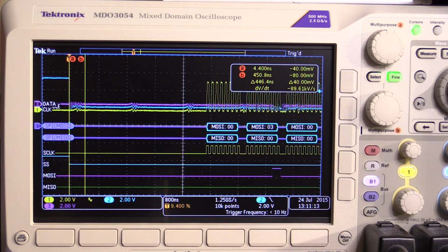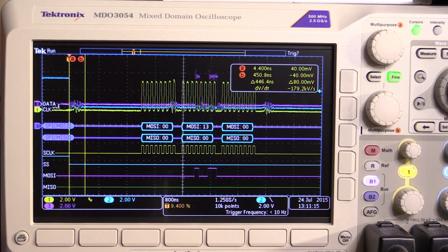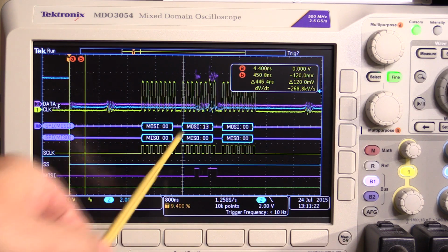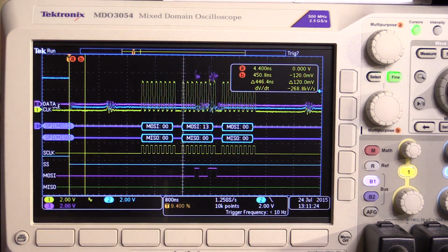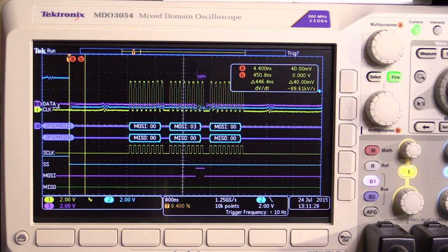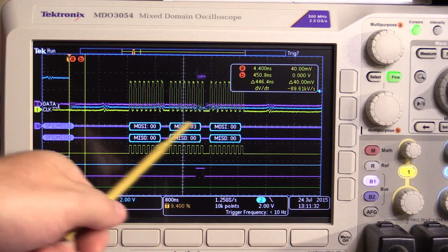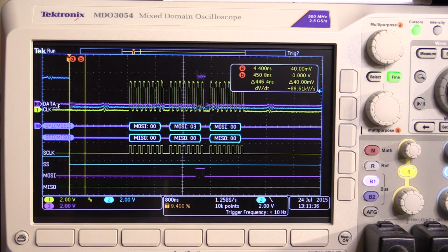So there's a bit being set and reset depending on the mode as I go in and out of unipolar, bipolar. And if I power up and down, you'll see that I've got an 03 or a 13, and the 1 on the first byte here is the bit that's telling me to power down on that group. And if I power it up again, you'll see that that bit goes away. The 03 here is to tell it that I'm working in bipolar mode.